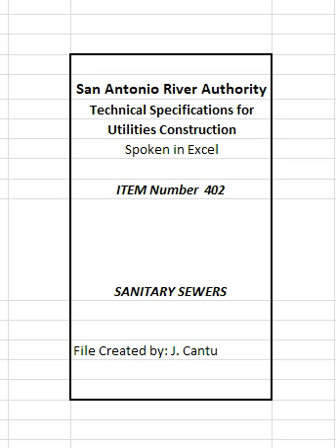402 For water main crossings. Where sanitary sewer gravity or force mains are to be constructed in the vicinity of water mains, the requirements of the design criteria for sewage systems of the Texas Department of Health/Texas Natural Resources Conservation Commission shall be followed.